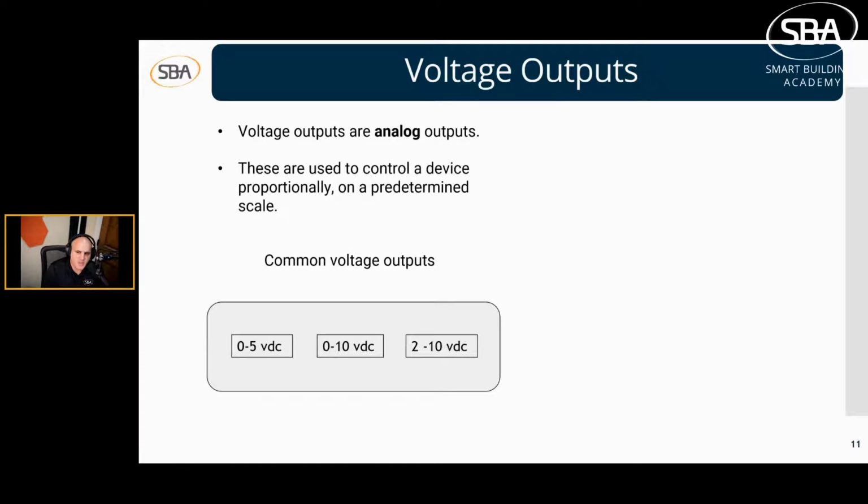You'll use voltage when you typically don't have a long run, you're not dealing with a lot of interference, and you also want to be able to measure in parallel and not in series. You'll use amperage typically when you have a longer run, more than 200 feet, you have electrical interference like in production rooms, hospitals, etc., and you also want the difficulty of having to either use an amp clamp or measure in series. Now, I'm just joking slightly there for those of you who have had to measure milliamps out in the field and don't like having to either find an amp clamp in your bag or go and actually disconnect the wires.